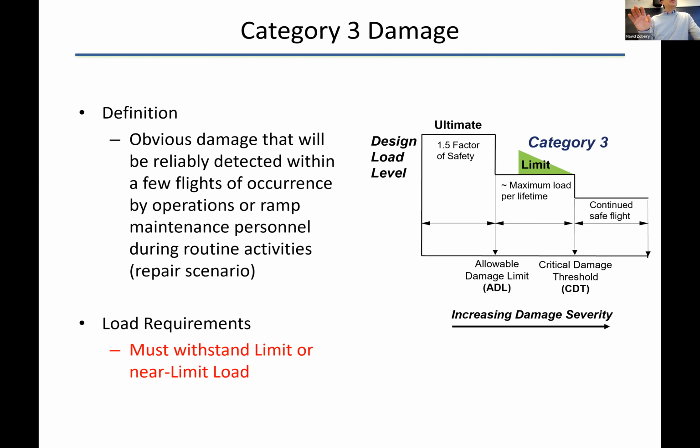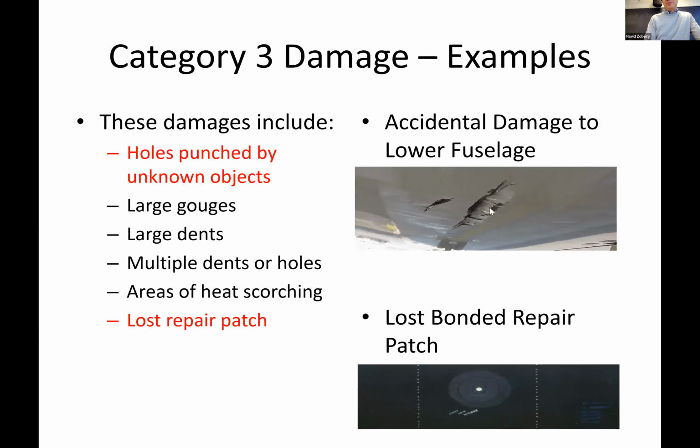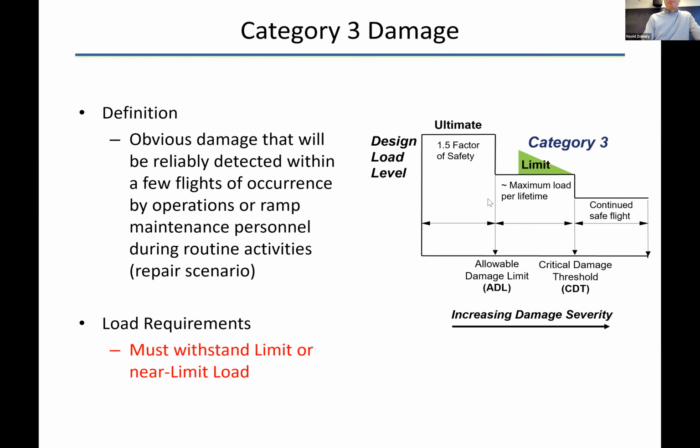These are one of those hidden safety factors. You expect this to reduce the performance of the structure, but the aircraft can fly if nothing happens to the aircraft after this severe damage. But you have to repair it as soon as you can, right? Because you don't have the safety factor, you don't have the fatigue reliability.